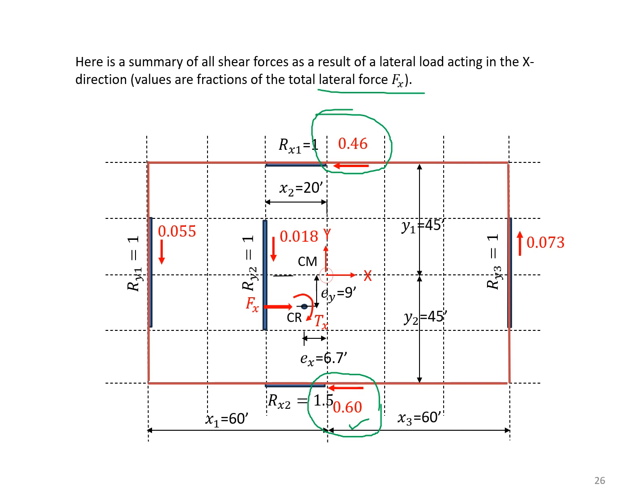Now in the y direction, remember we got 3 forces. We are showing them in here. A small amount. Nevertheless, there is a shear force developed. And also notice that we put the force at the center of mass, rather at the center of rigidity, and then apply the moment in there. The eccentricities are also shown. EY is equal to 9 feet, EX is equal to 6.67. But again, these are theoretical values. Remember, in reality, we added those 5% percentages.